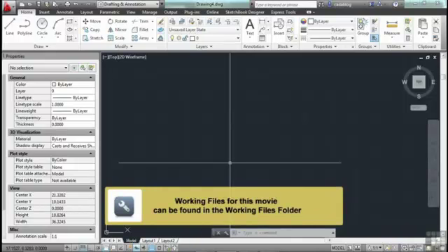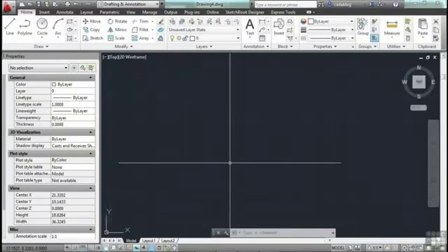Blocks are great tools that enable us to recreate similar line work rapidly. They can also contain metadata in what is called attributed blocks. A block attribute is a label or tag that essentially attaches data to your line work. Some examples of this data could be a part number, price for that part, specific comments, names, cost, manufacturer, anything you can dream of.